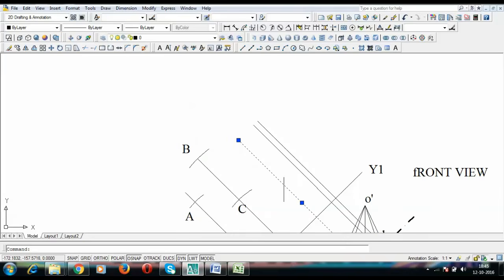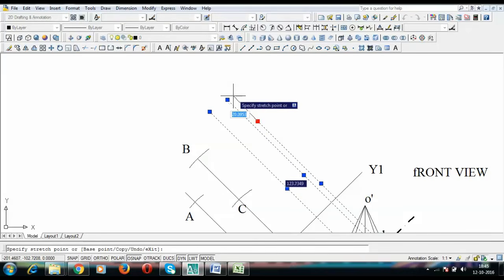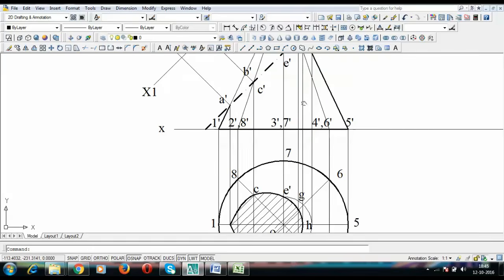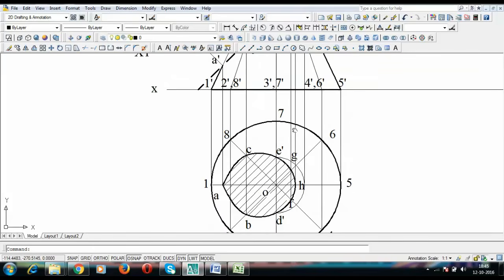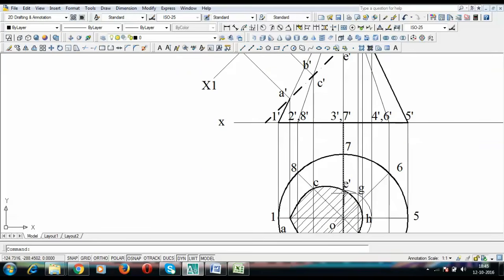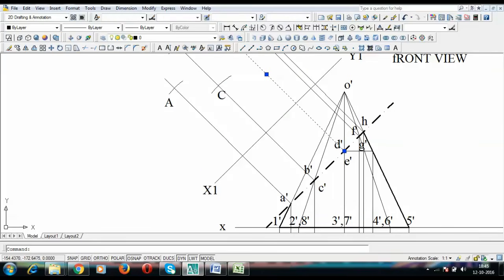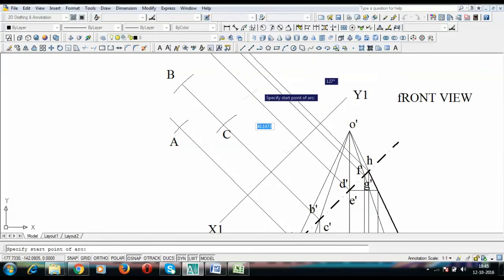Now, why not extend these lines? Let us extend them. Now, let us locate point E. When you take an arc for point E, it works out as 40. So point E is along this line. You need to take an arc of length 40 millimeters. I'll write 40 over here and then move in this direction, so this automatically becomes my point E.